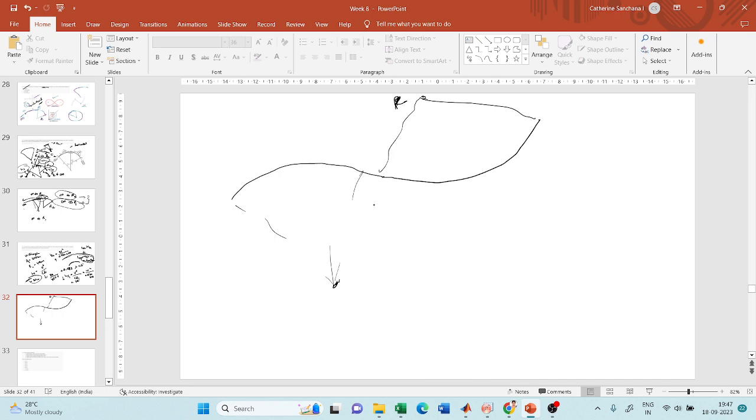Right? Now, as we saw earlier, the transition curve at this end and this end will not have a problem. But in between the curves also, you have to provide a transition curve. Why should I provide a transition curve, even if it has the same radius? So reverse curves can have the same radius, right? Unlike compound curves, these curves can have the same radius, but they are in the opposite direction.